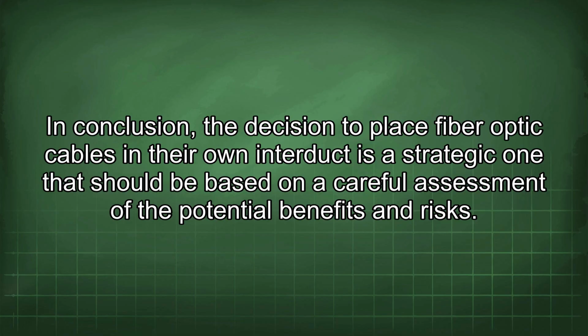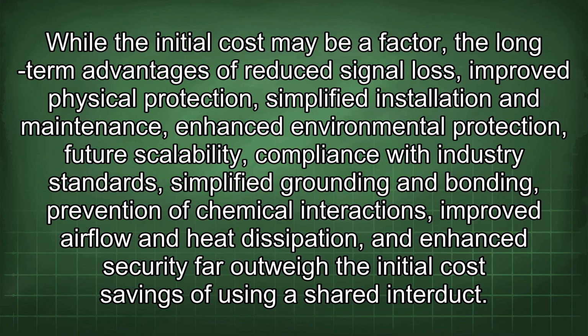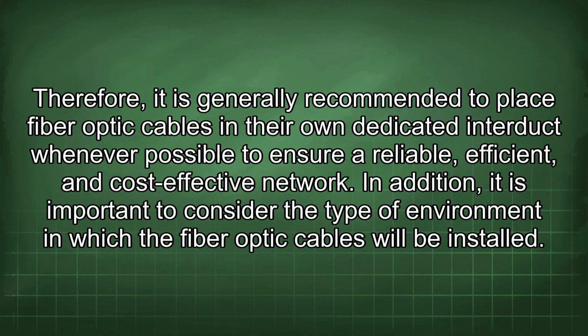In conclusion, the decision to place fiber optic cables in their own interduct is a strategic one that should be based on a careful assessment of the potential benefits and risks. While the initial cost may be a factor, the long-term advantages of reduced signal loss, improved physical protection, simplified installation and maintenance, enhanced environmental protection, future scalability, compliance with industry standards, simplified grounding and bonding, prevention of chemical interactions, improved airflow and heat dissipation, and enhanced security far outweigh the initial cost savings of using a shared interduct. Therefore, it is generally recommended to place fiber optic cables in their own dedicated interduct whenever possible to ensure a reliable, efficient, and cost-effective network.